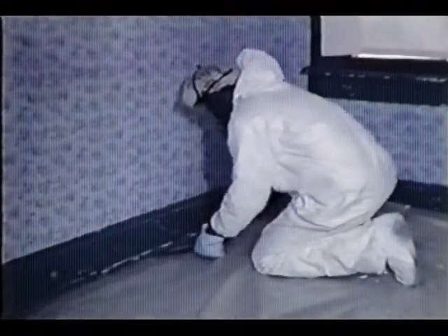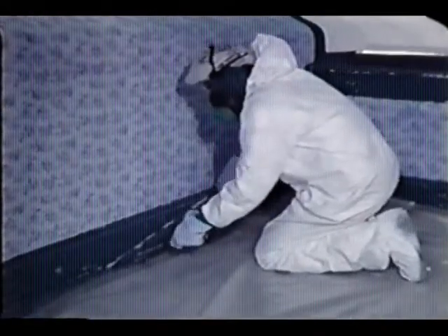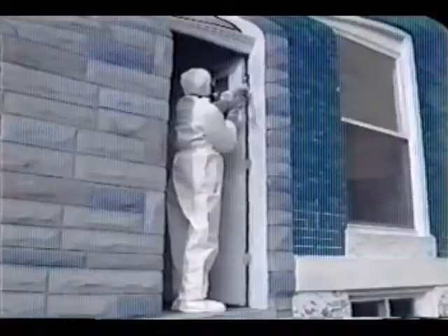The most desirable abatement method is probably building component replacement because it offers a permanent solution to a lead-based paint problem with minimal dust generation. Components that can be replaced include doors, windows, trim, porch and stair railings, and other removable components such as cabinets.